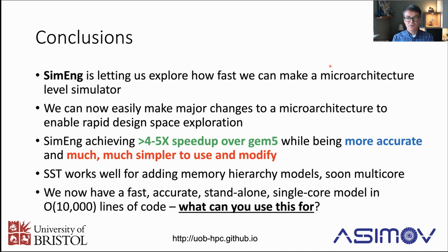And you can actually play around with where SME would connect to. Is it going through L1 or L2 or even L3 or even straight to DRAM and not using any of the caches? You can try all that in simulation and see what happens. But yeah, these things are very complicated. They're almost like little out of order engines themselves, modern load store units, and we've got pretty good models of that in SimEng now.